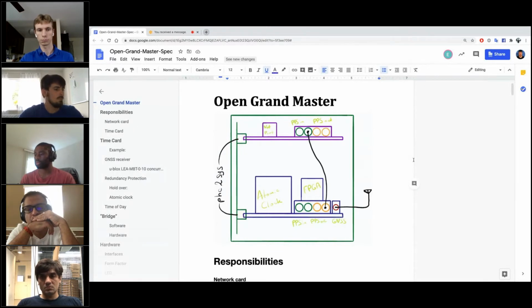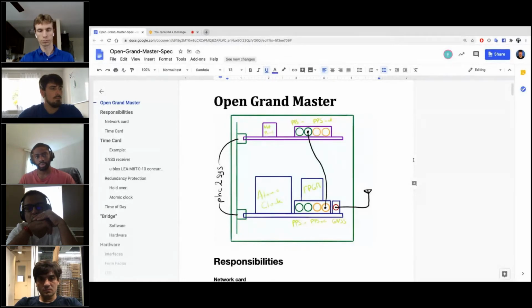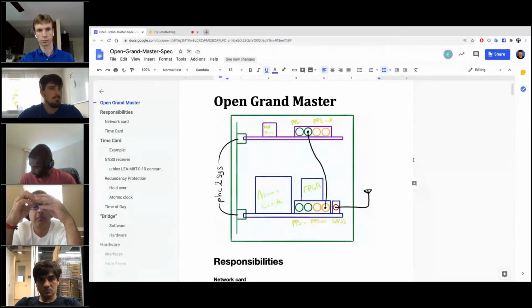With that, I will jump in for just a few minutes on how we are going to do that with our network card. Actually, it's pretty easy. We have an internal clock inside the NIC, of course, otherwise we cannot timestamp. Every time we get a PPS pulse, we snapshot the internal clock at the PPS signal arrival, and we send it to the software. So the software gets a message like, you got a PPS in at 8 o'clock and 200 nanoseconds.